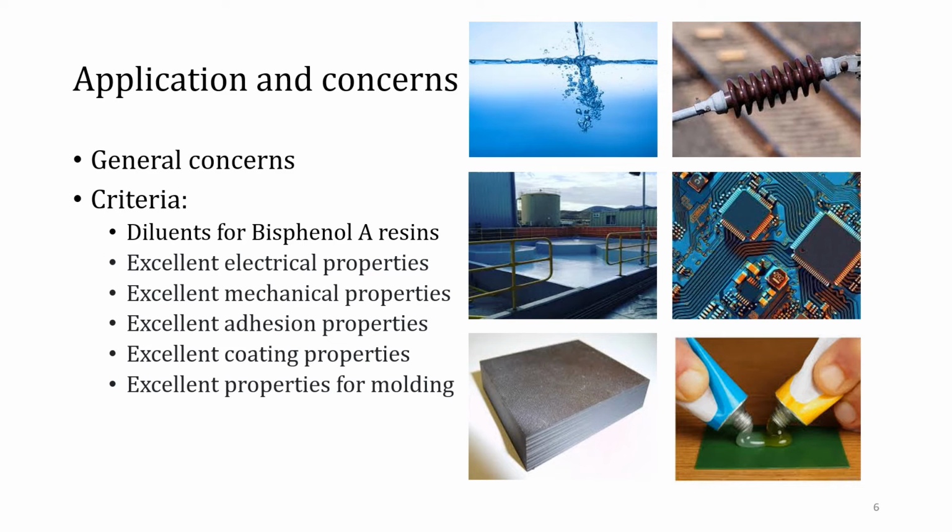Cycloaliphatic epoxy resin can also be used as a resin component in plastic molds. The resulting cured product has good heat resistance, good mechanical strength, small volume shrinkage, and high accuracy, suitable for making precise parts. Compared with the metal mold, it has the advantages of easy processing, low price, light weight, and it is conducive to molding operation. In addition, the cycloaliphatic epoxy resins can be used as a modifier of the resin and plasticizer, a stabilizer, an oil additive, and a heat-resistant optically transparent material.